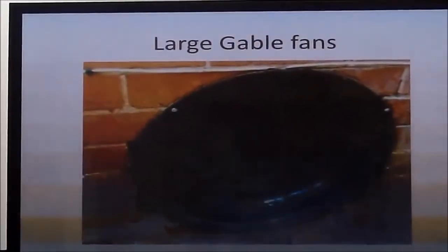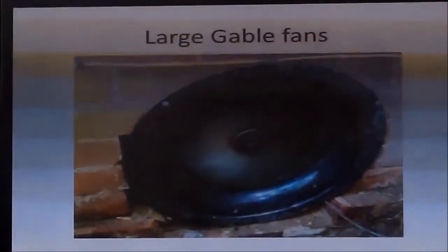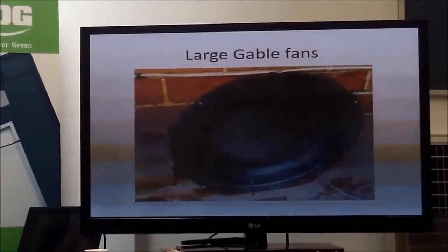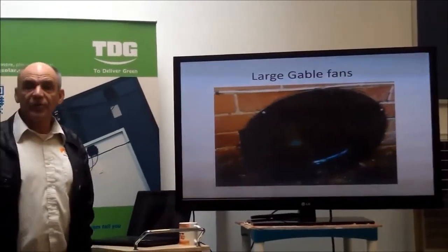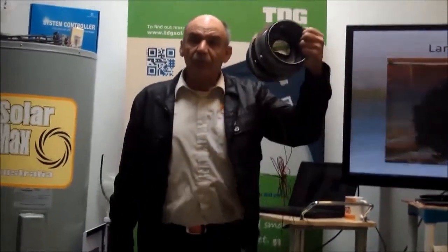And large gable fans. These are about 330 diameter and they can do around about 3,000 cubic metres an hour. So it's about nearly 10 times what this fan will do.